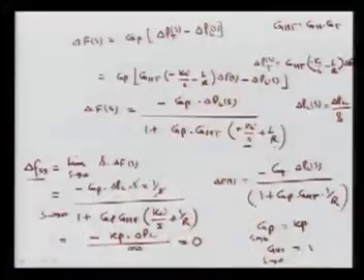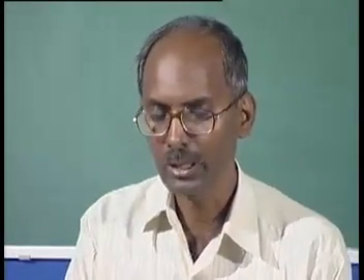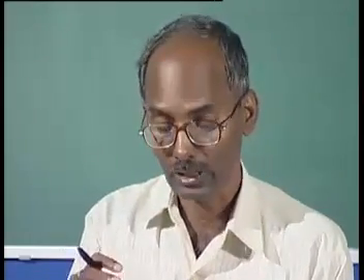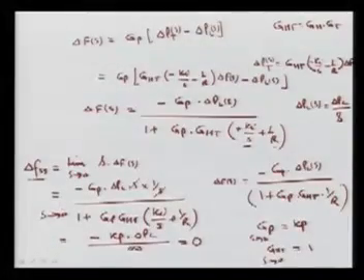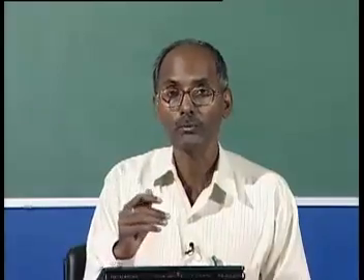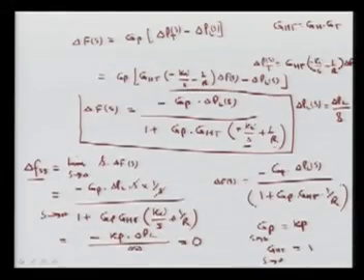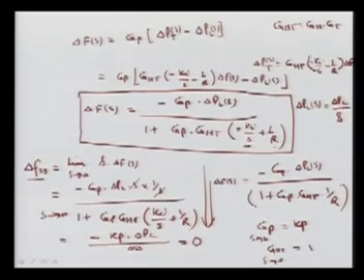So this is the steady state response of this whole secondary ALFC, that is, secondary area automatic load frequency control. Similarly, we can go for the dynamic performance, and we will see that Ki plays a very important role for the performance of the dynamic response. So here this is the complete closed loop transfer function, for which we saw the static performance, and in steady state we found that it is 0, and that was required.